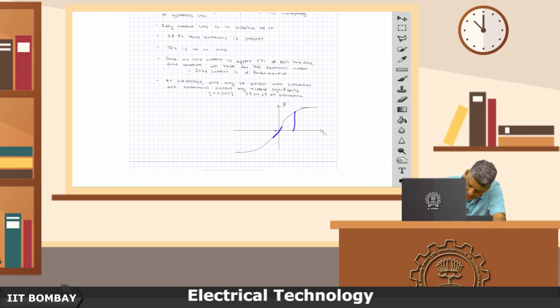The knee point is, if you take a tangent here, and when it saturates, you take a tangent here, where they intersect, that point is sometimes called B knee and this would be H knee. Knee is where it turns, just like in our leg where you can bend it. So, where the characteristic bends, I will draw it slightly better than this.